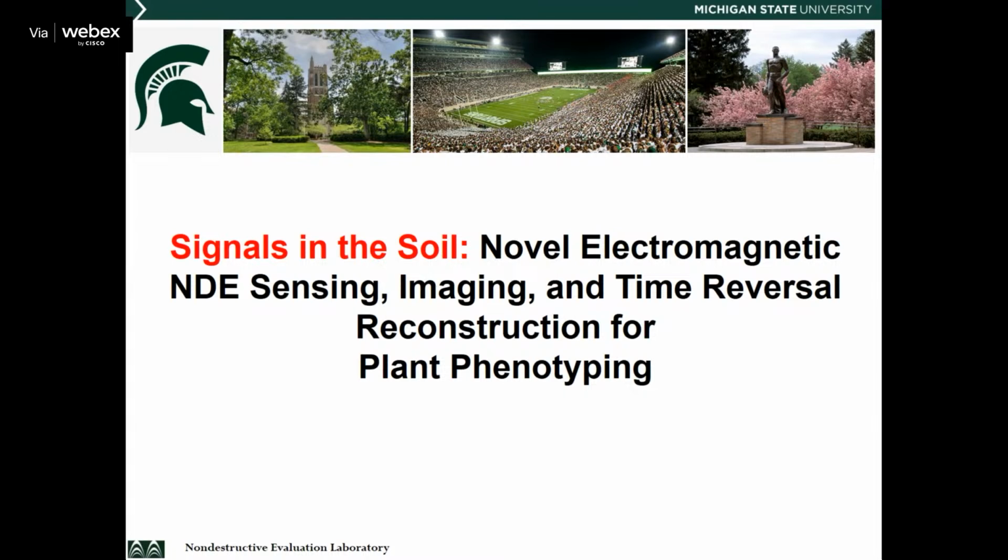This will be really challenging because we're dealing with measurements where the signals are in the soil. And soil in itself is a very challenging material that will attenuate signals. Think about ultrasonic signals in the soil. They will not propagate a very long distance because of the air and the different composition of the soil, which will attenuate the mechanical waves significantly.